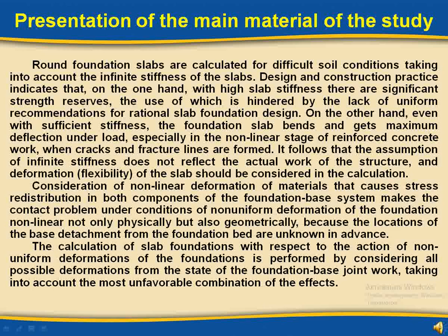On the other hand, even with sufficient stiffness, the foundation slab bends and gets maximum deflection under load, especially in the nonlinear stage of reinforced concrete work, when cracks and fracture lines are formed. It follows that the assumption of infinite stiffness does not reflect the actual work of the structure, and deformation, flexibility, of the slab should be considered in the calculation.